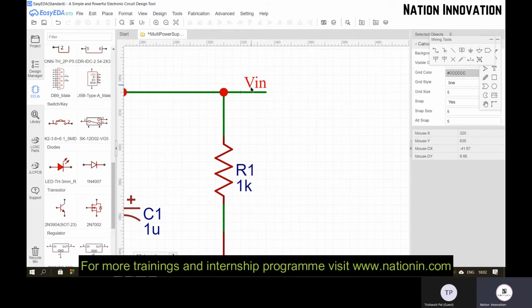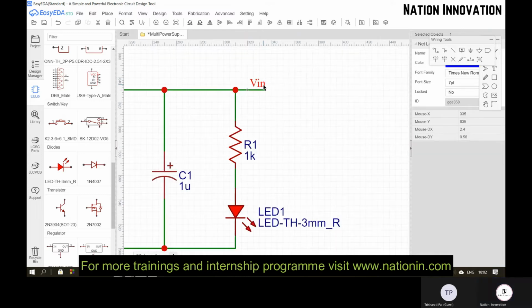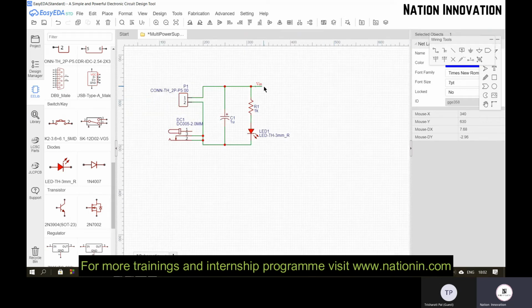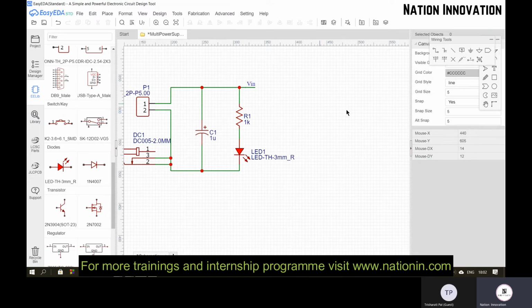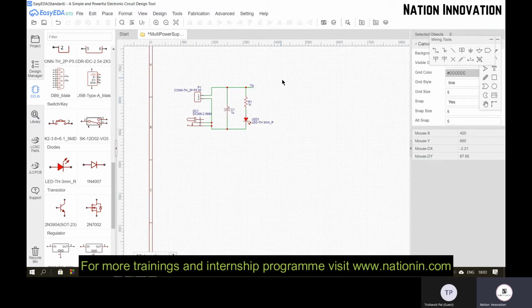This is the special function, that is the net flag. So you no need to connect an extra wire to whatever units you are going to make. You can directly name them by using this net flag. If you name the name here, you can use the same name to rename there. Like I will show you how to do that. This is the power supply.